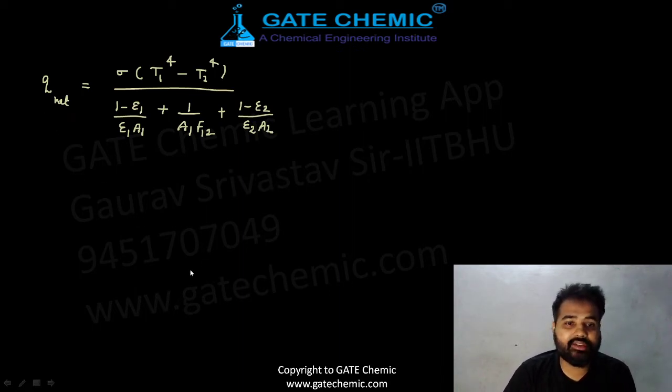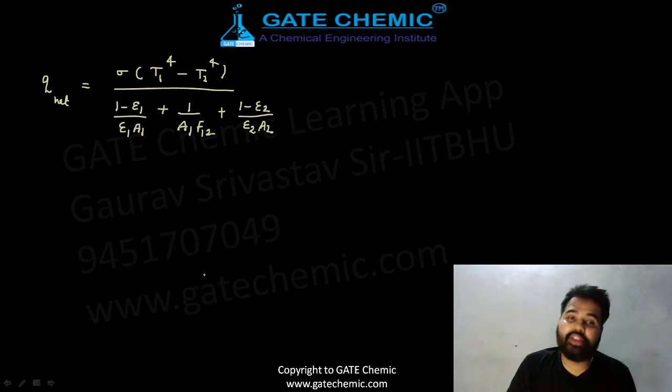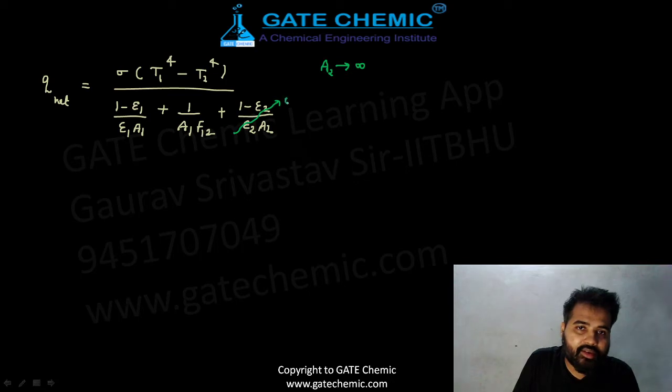Now this is the case of a large enclosure. If a large enclosure is given there, that means A2 tends to, beta, what? A2 tends to infinity now. So this term you can write as 0. After writing that part as 0, our above equation becomes sigma, and I'm also taking this A1 common from the denominator.